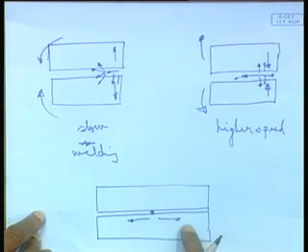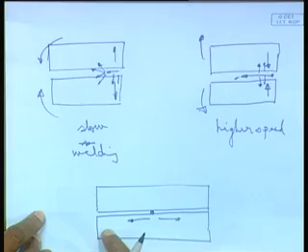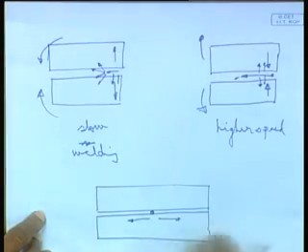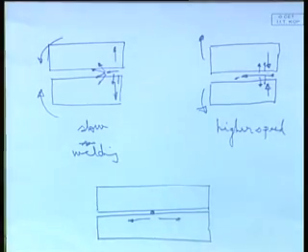Then this will negate the effect of this. Go simultaneously outwards. So, one from the center to the positive side and center to the negative side, each one will cancel the effect of the other. So, there is no problem. So, that is the only solution. When a long welding is done, it is necessarily to be done from the center going outward. You cannot do it from one end.